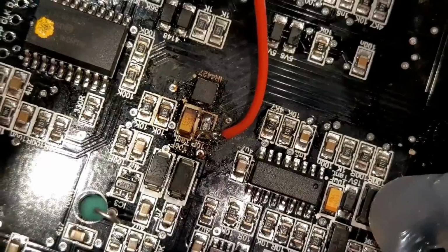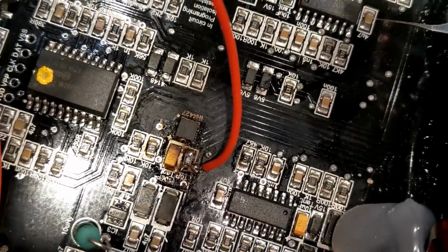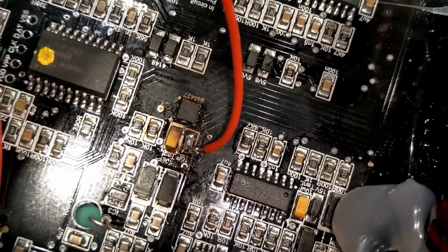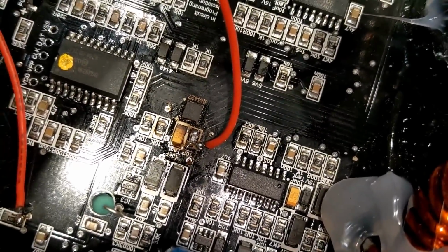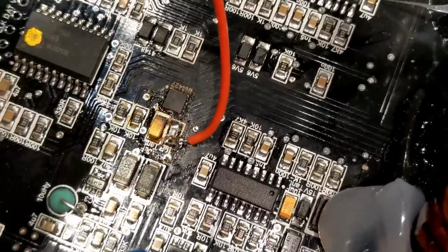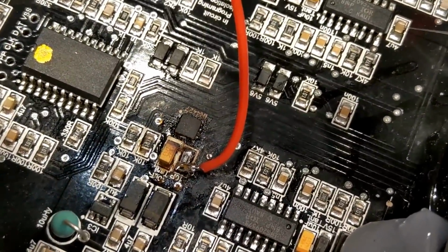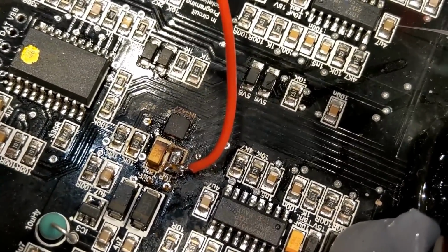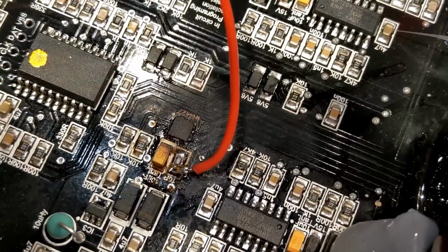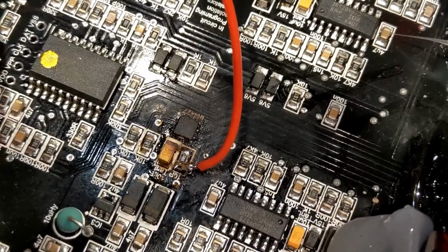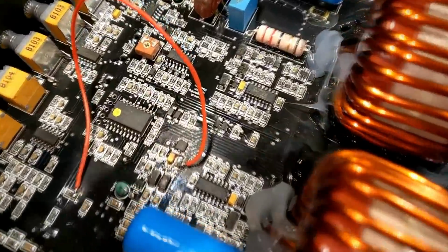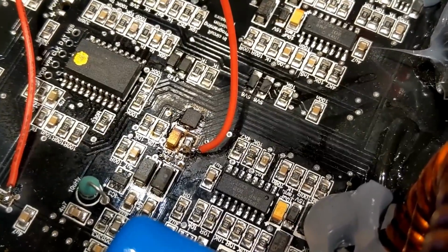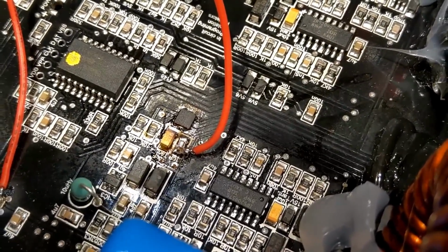And I thought that that was probably about it. It's probably just gone to the driver, just gone to the resistor, and then it's all good to go. So replace the resistor, replace the driver, and what I noticed was that when I turned the remote on, the VCC for this chip, which is supposed to be battery voltage, supposed to be stuck at 12 volts, was going down to ground. So with the amplifier off and the power into the amplifier, I was getting 12 volts at the VCC, but then as soon as I applied the remote, it sunk down to like 2 volts. I was like, wow, okay, what's going on here?